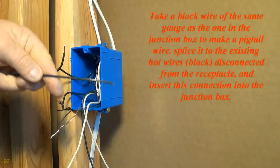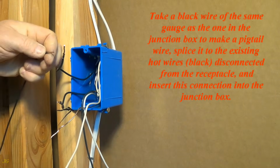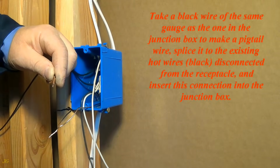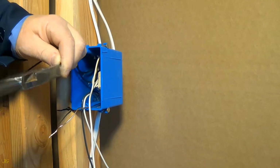Take a black wire of the same gauge to make a pigtail wire. Splice it to the existing hot wires, black, disconnected from the receptacle, and insert this connection into the junction box.